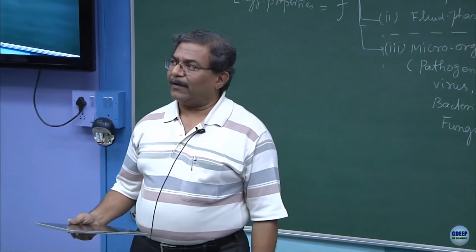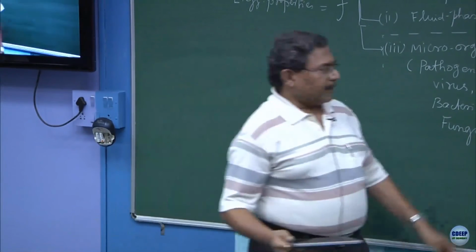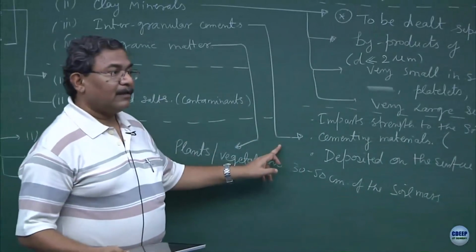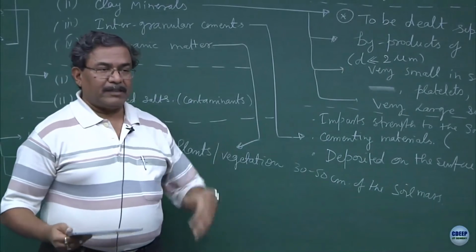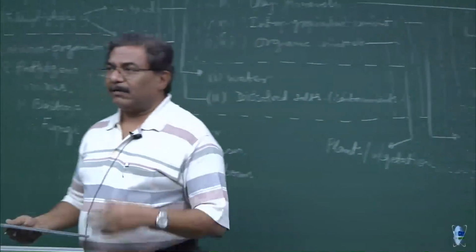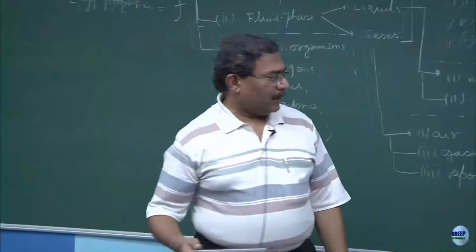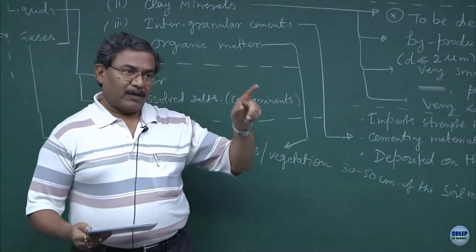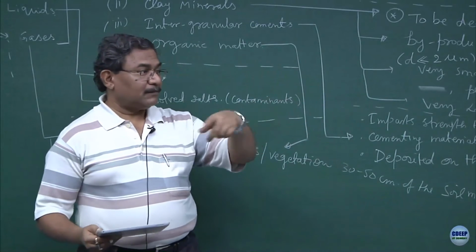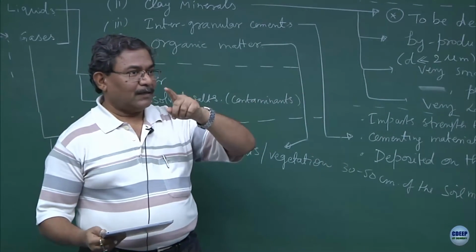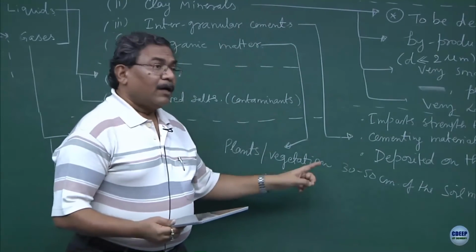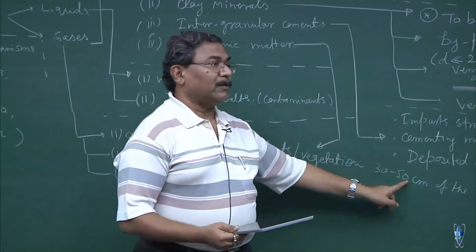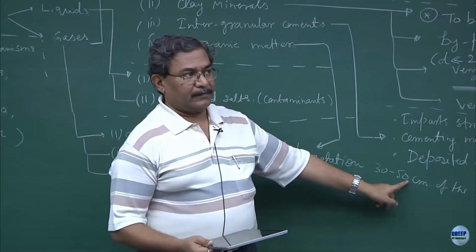Understand? Why? This becomes a layer in which agriculture is going to prevail better, because of the organic matter which gets decomposed when it comes in contact with water, when it comes in contact with atmosphere and so on. But as far as civil engineering is concerned, geotechnical engineering practices are concerned, I will make sure that my foundations rest beyond this zone, which is inert.